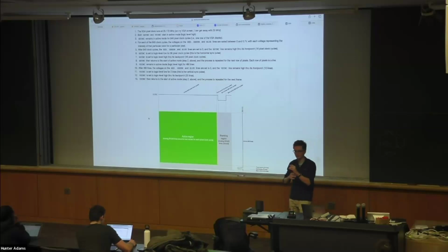So another bug that you might see is for your text that you're writing, or perhaps for your histogram at the bottom, if you find that they are flashing, the flashing is a symptom of you erasing and redrawing that big block of the VGA 30 times a second. It's something like the update rate of the VGA screen beating against the update rate of your pixels.